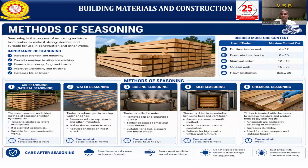Okay. In kiln seasoning, the timber is dried in a controlled kiln using heat as well as ventilation. It will be the fastest method when compared to the other methods. So moisture content can be controlled, suitable for high quality timber and furniture purposes. So this also takes 7 days to a week for the seasoning.